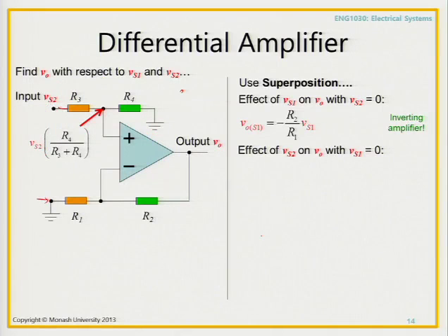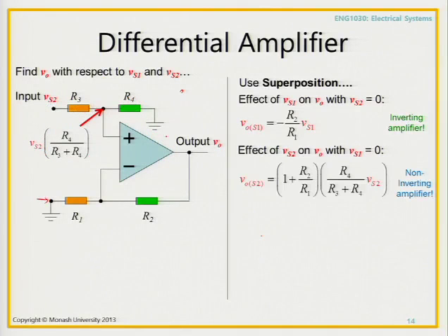So imagine these aren't here, and this is just a value here. And remember, if you turn this resistor downwards, then it looked like something we saw last week, which was a non-inverting amplifier. So the gain of a non-inverting amplifier was 1 plus R2 over R1.